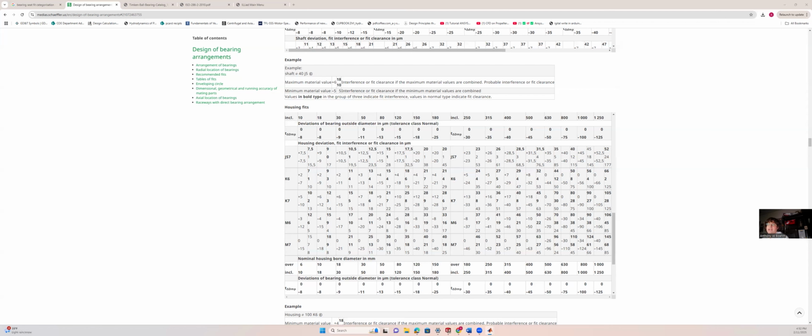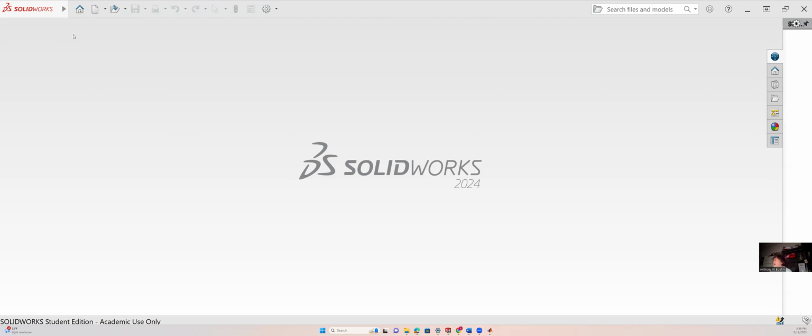And I'll leave it up to you guys to do the actual math. Certainly that 8 microns of interference falls neatly between the 2 and 10, even up a little bit more towards the 10. So that's what we're going to use the equation for, our final guidance as to what we're actually going to make the dimensions. Okay? So now we could take that information and go to SolidWorks and start designing our gear train.